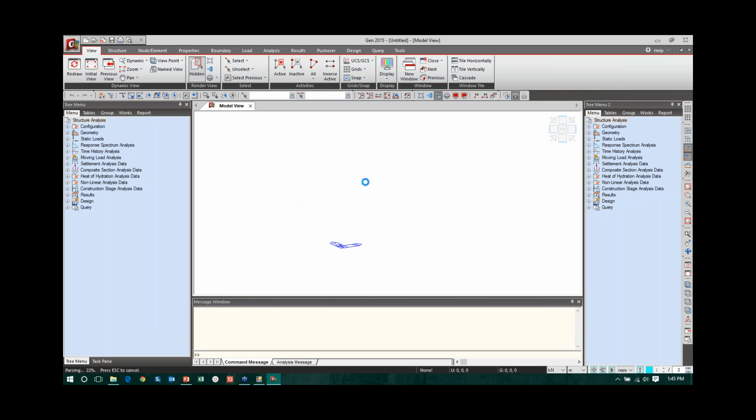So all your element beam loads and pressure loads are taken, and plate thickness, solids and beams are imported. Beam offsets, plate offsets, boundary conditions, inclined boundary conditions, spring supports, everything is imported from the STAAD file. All types of supports and all types of loads are imported, except seismic and wind loads and floor loads, which are defined with Y range and X range. Apart from that, all the other things are imported to the program.